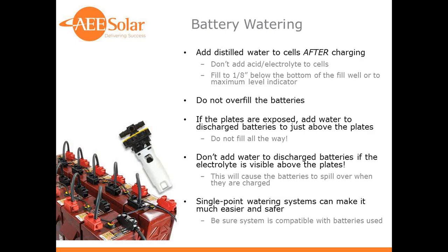A fully charged battery, the electrolyte level should be filled to approximately 1/8 of an inch below the bottom of the filler well. After you remove the cap, you can see the bottom of the well there. But don't overfill the batteries. When they're charging, the electrolyte will expand, and you could have an overflow, which is going to be not only a mess, but a loss of active material from the battery.